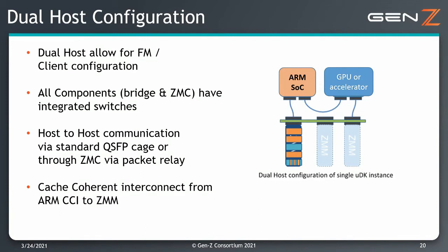At the very bottom here, we show both blue and orange in little stripes, and this is a representation of shared memory. So let's say there's a database that both processors need to reference to execute a function. You can allocate sections to sharing, and so both processors have equal access to this memory. It's much easier to think of as a read-only area. However, they can be write and read, such that the processors can hand data backwards and forwards to each other. But this is an example of the IP that we've seen earlier in operation, the interconnects and the cables, and the pluggable modules there.